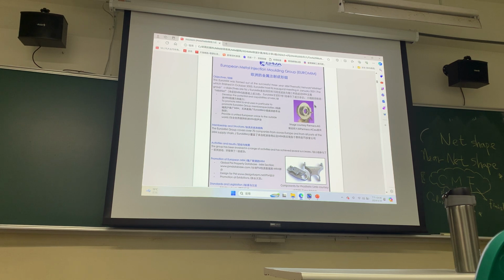Okay, don't just say, oh, yellow. My God, what is yellow? Oh, blue. No, I'm sorry. Please give me the Pantone color. Please give me a golden sample. We call this one limitation samples. You give me the limitation samples, I follow this one, and this one has a middle, high, and low. So 1, 2, 3. At least give me a range, a window, not only yellow, but gold.